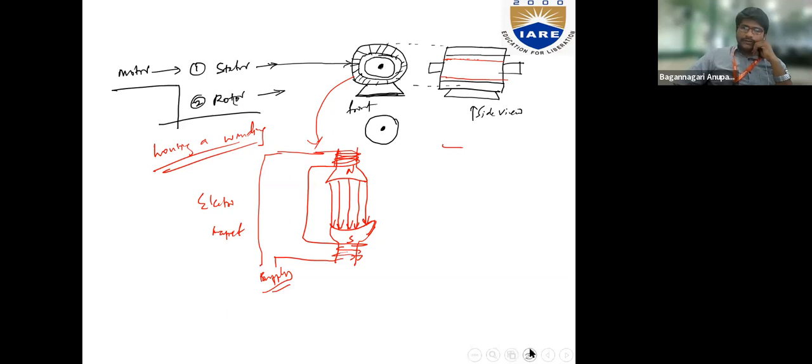Whenever we have such a case, suppose this whole thing constitutes a stator, right? What's the function of the stator? To form a stationary pole mechanism or stationary magnet, say the stator field. Now, when we consider a rotor, what does a rotor consist of? The rotor consists of the same winding. You will have some slots here, right? In those slots, we will place some windings. Here we can place some windings, and here as well.